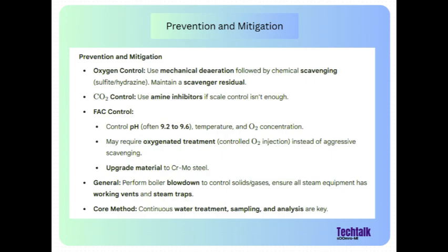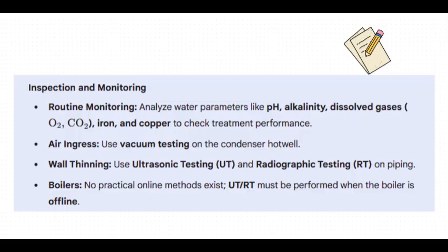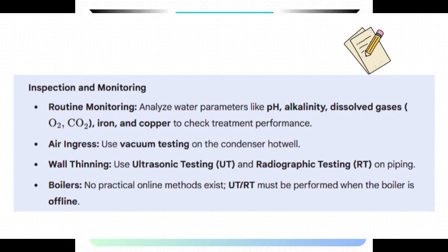Okay, this brings us to keeping watch, monitoring. All this delicate balancing relies on knowing exactly what's in the water, right? Constantly, you need rigorous sampling and lab analysis. What are the key things being measured? Well, obviously pH, conductivity, which tells you about total dissolved solids, alkalinity, hardness, and chlorine or biocide residuals. And the gases, of course. And definitely the dissolved gases, O2 and CO2. Plus, you track indicators of ongoing corrosion, like levels of iron and copper in the water. Spikes in iron or copper mean your system components are dissolving. Exactly. It tells you the protective layers are breaking down somewhere.